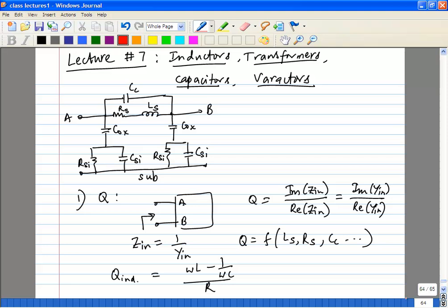But you'll be trading off: the underpass will use an even lower metal layer, so that underpass may dominate your series resistance, for example, okay? So there are lots of trade-offs depending on the type of inductor you choose to design.